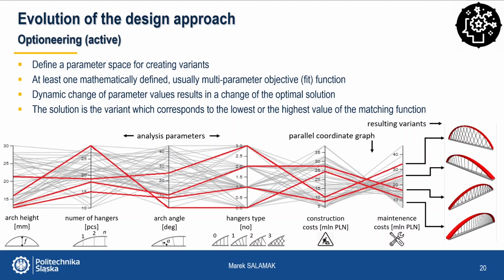The example uses four parameters: the arrow of the arc girder in meters, the number of hangers, the angle of inclination of the first hanger, and an enumerated type parameter identifying the arrangement of hangers. 0 means vertical, 1 radial, W type is 2, and finally mesh is 3.